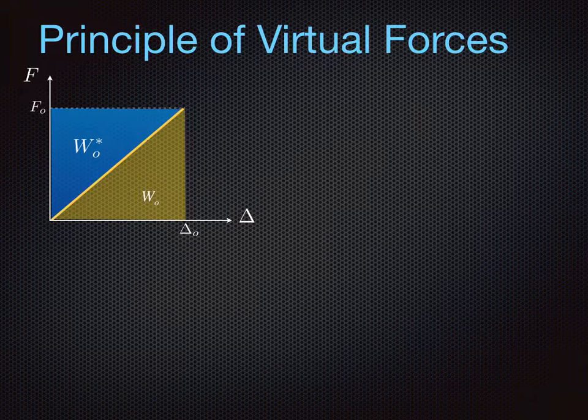Okay, so now we're again in equilibrium position, and this time instead of perturbing the deformations by an arbitrary amount, we're going to perturb the forces. When we do that, we're going to keep the displaced deformed state constant, just like what we have done in the principle of virtual displacements, in which case we had kept the force system constant and only perturbed in a virtual manner the displacements. Here we are keeping the deformed shape constant and perturbing the external forces by an arbitrary amount, here denoted as a delta F.